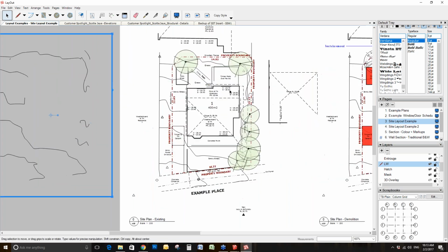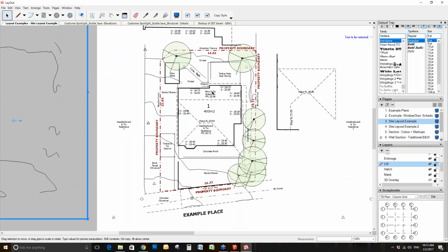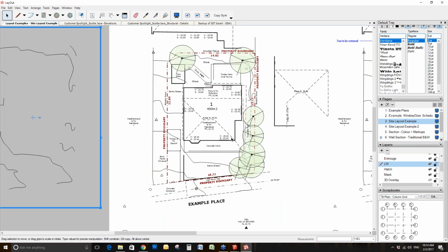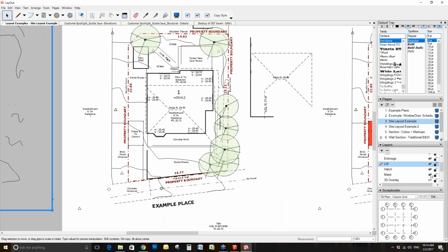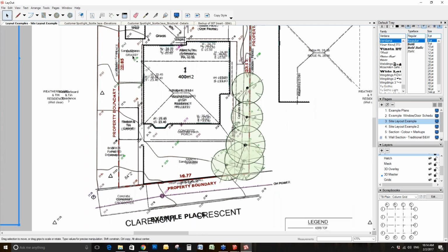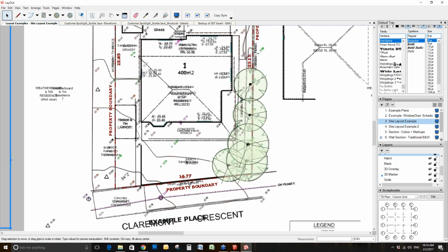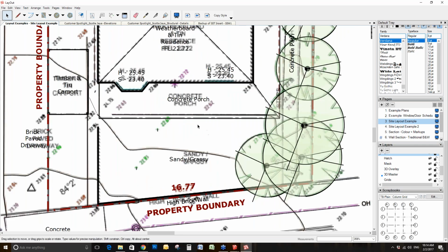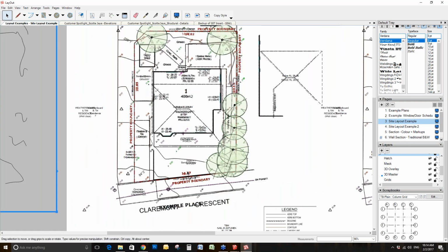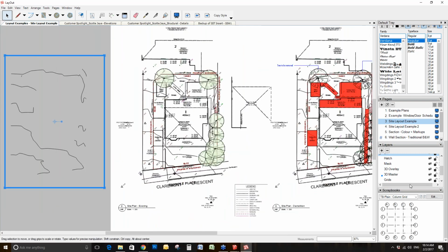So typically I will just go through and quickly write in the actual annotations that I require. I've even got an overlay here, which I never showed you before, but that actually is a PDF, and the PDF is being scaled using PlusSpec, and it gives me a lot of other information that I might want to copy rather than trying just to guess. If I wanted to put all of these symbols in there, I could, and they're going to be 100% accurate. It's not a hell of a lot of time, so I don't think it's a time waste to do that.